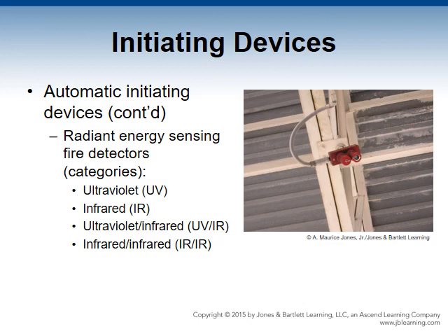Flame detectors work in a specific environment with specific fuels. Spark and ember detectors are not fuel specific. They are installed on or near equipment where material moves through a duct line or a conveyor belt. They operate in the IR range and must be installed in a closed, dark environment. When they detect a spark or ember, a signal operates suppression equipment.